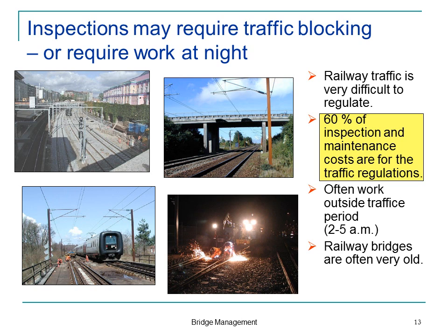Suppose you are an engineer, you are out there doing an inspection. How many seconds do you say you could be distracted by an interesting detail? If we say 20 seconds, it means that the train can move 1 kilometer at least during these 20 seconds. This is why you have a guard standing by, and they say this is the maximum distance it can be away from you. Because his job is not to say, dear sir, I think it would be a mighty good idea if you step off the track.